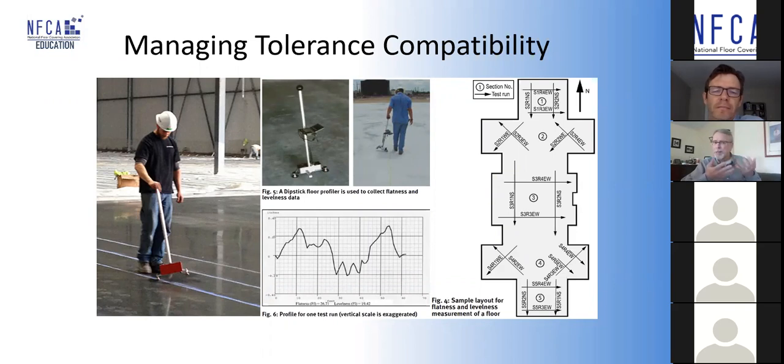But keeping in mind that because concrete changes, the tighter the tolerance for the concrete on that day 3 measurement, the more it will change over time, meaning that your FF50 could change up to 70% by the time the floor installer is on site, which means you could have something like an FF15 or an FF12 when it actually comes time to install your floor. So pushing up the tolerance doesn't solve the problem.